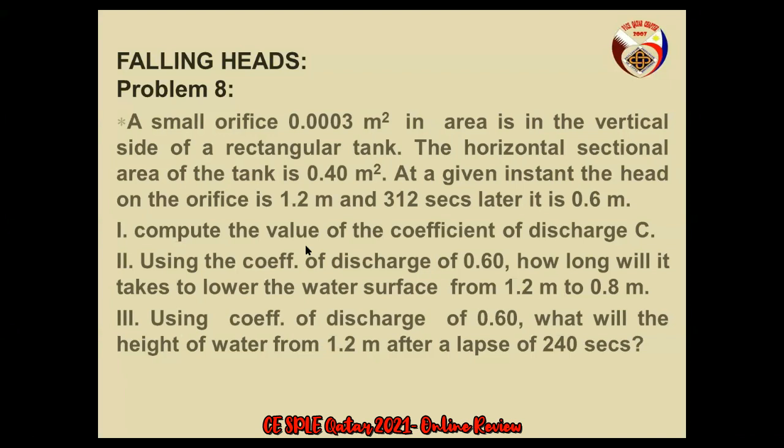Eto, small orifice in area, so 0.003 square meter in the vertical side of a rectangular tank. The horizontal section of the tank is given, so constant area, 0.4. Madali lang ito. At a given instant, the head of the orifice is 1.2, and 312 seconds later, it is 0.6.